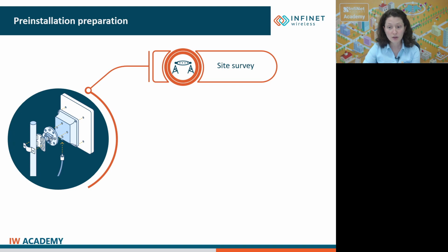The influence of the trees can vary depending on the season, so keep in mind that during spring and summer, the leaves can absorb some of the radio energy. Therefore, when installing during the cold season over forests and trees, try to achieve a higher fade margin. Also install the antennas as far as possible from other antennas, ensuring at least 2 meters separation.